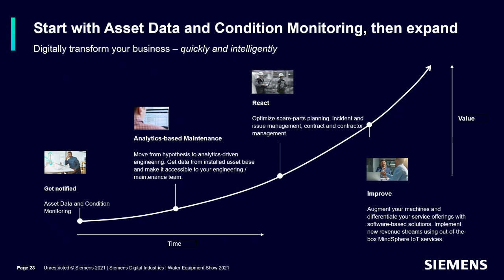We need to understand how deep do I actually want to analyze this data? Do we need to have full vibration analysis, FFT analytics? How will I then use and allow me to react in an appropriate manner with that data? And how do I use this data then to improve or optimize the process? It's important to have a step progression so value can be measured and supported through a return on investment program, which then allows the funding of the next level of investment.